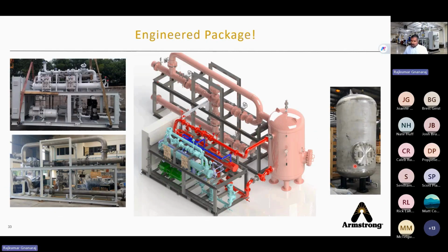For any heat pump, in most of the applications, you have seen a tank. Heat pump needs a tank. If the hot water demand goes to a batch heating process, or if the load swings a lot, then you need a buffer tank here, because the biggest misconception most of us have is considering heat pump as an instantaneous hot water heater. Heat pump is not an instantaneous hot water heater, because imagine the heat pump provides hot water and then it goes to a specific heating process load.